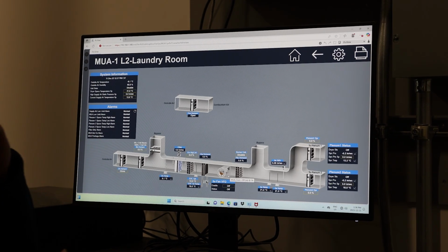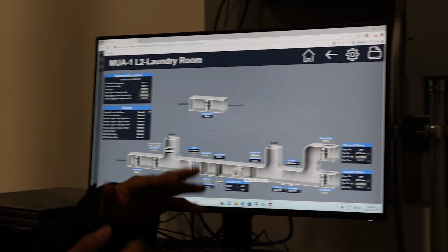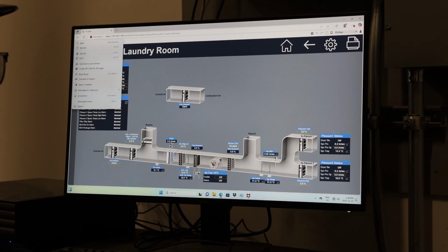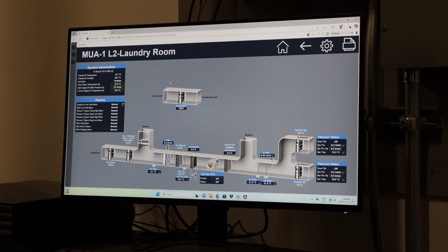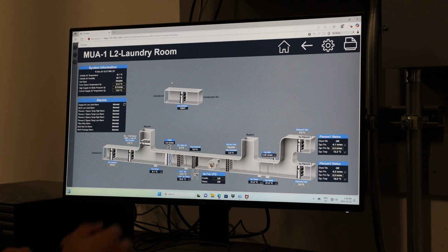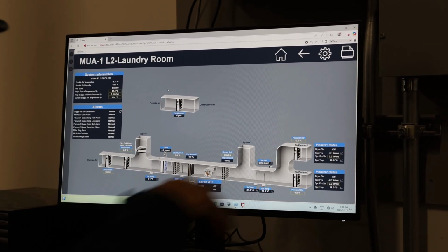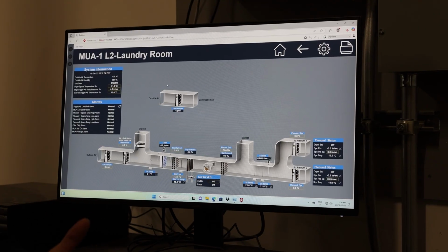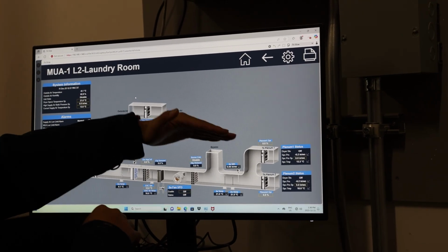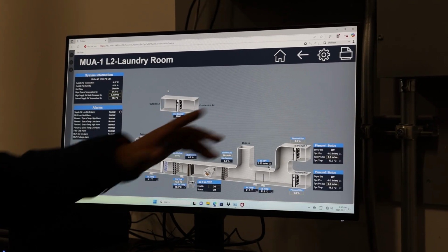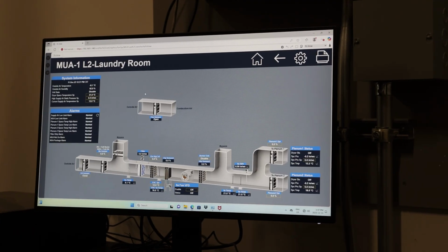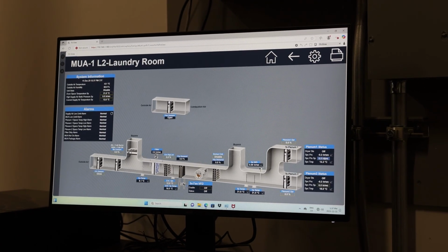But how are we maintaining the space temperature is based on this, right? That's the case if we only have 1 dryer running, right? Likely we only need little air to the space. If we have all the dryers running, bypass will close, full fresh air to the space. As long as the plenum temperature is maintained well at 0 degrees.